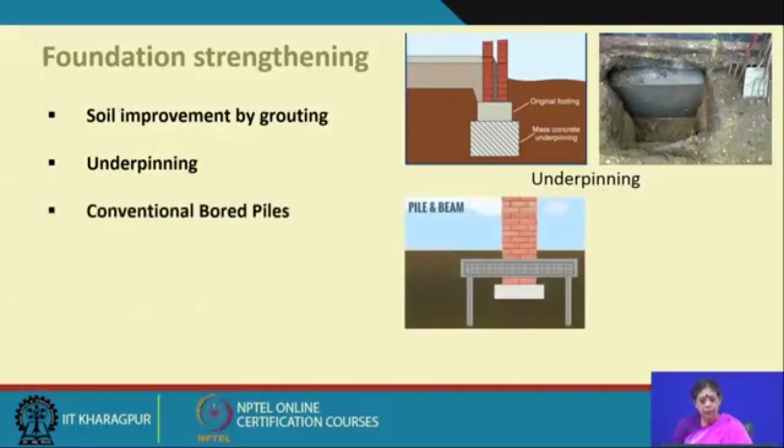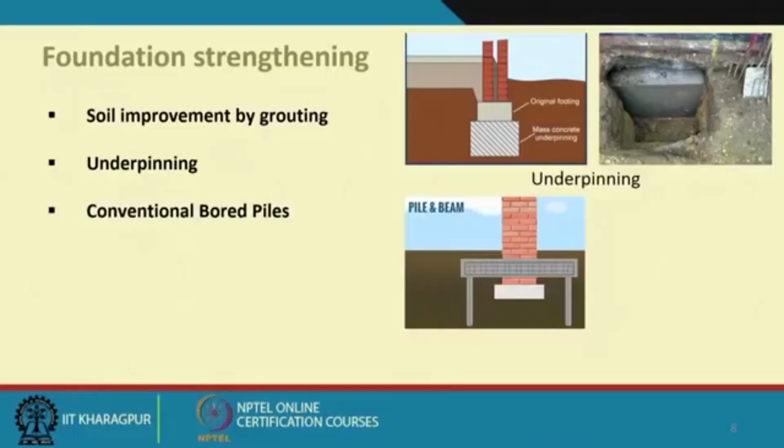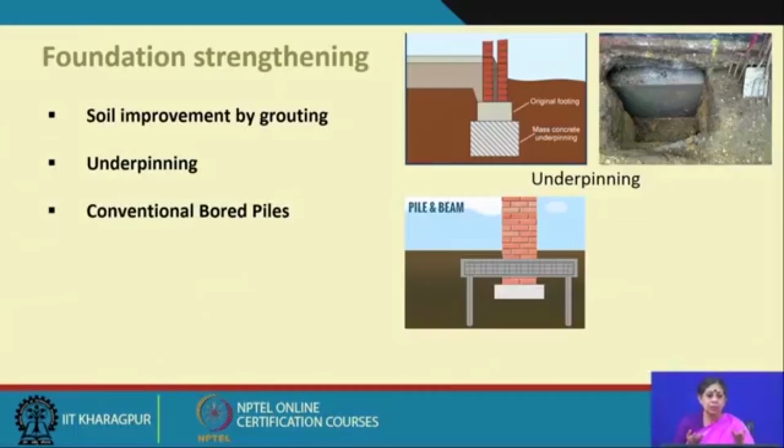And conventional bore piles. So, piles also can be done, when you put the piles under the structure. In this particular case, what you see is that a new sort of bed has been prepared, and this is now supporting on a symmetrically balanced arrangement. Sometimes it can be asymmetrically balanced, where the piles can be on one side, two piles, and then the new structure can act as a cantilever and support the foundation. So, depending on the situation, the pile and this beam can be a possible way.